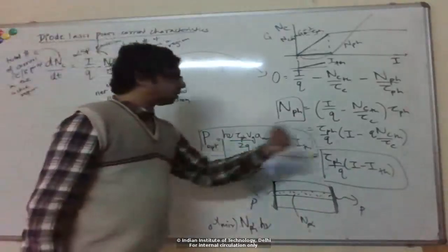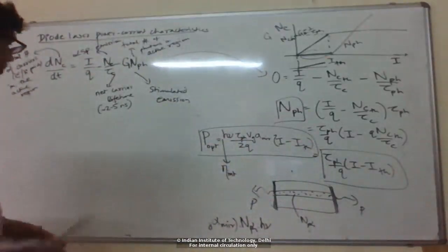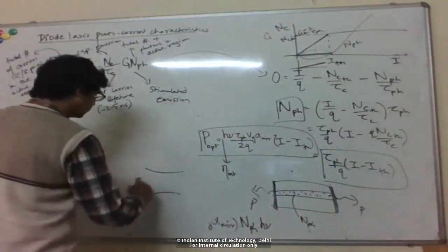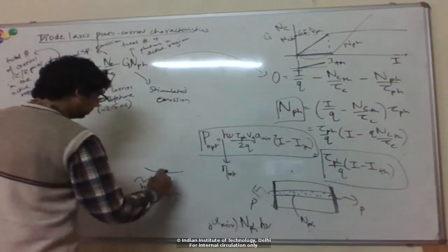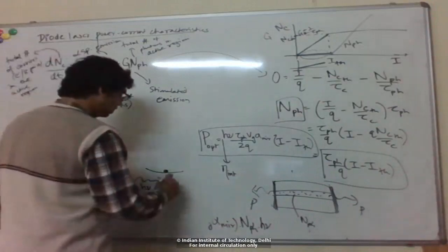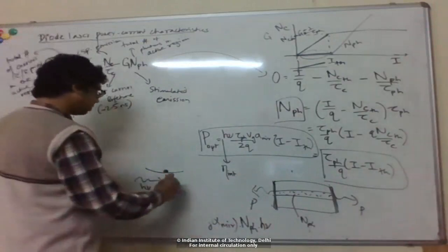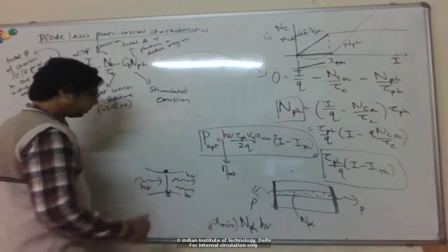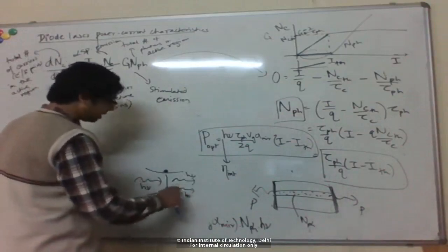For the laser, now we've gone into stimulated emission. For stimulated emission, one can also define an equivalent quantity where, let's say I have an incoming photon, and it stimulates a recombination of an electron-hole pair. Now this recombination can again be radiative or non-radiative. It can be radiative, which is what I want, but there could be some other parasitic processes where the stimulated emission does not happen.